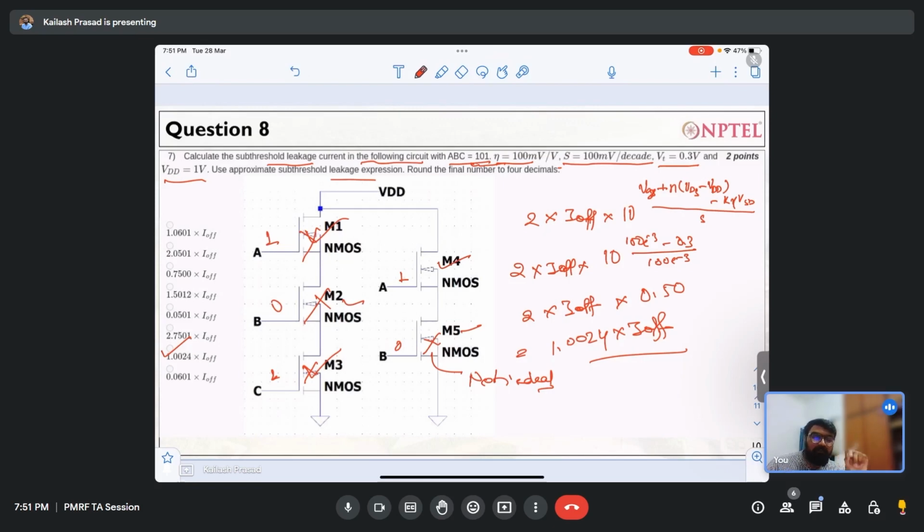But if your transistor is very leaky, what will happen? The pacemaker will stop working after some time, because all the battery will be drained. In the pacemaker, you don't want your transistor working at 1 gigahertz, because the pacemaker beeps at our heartbeat, 72 beats per minute. It can be extremely slow, but the only concern there is the power. The lifetime should be as high as possible. There, what I've said, the high threshold voltage transistors become extremely important.